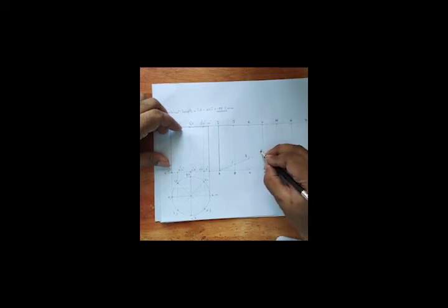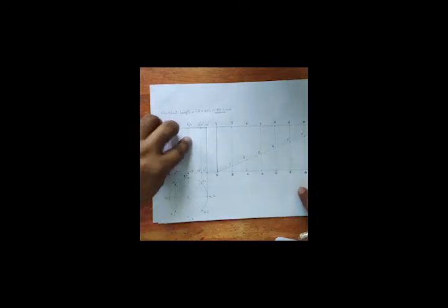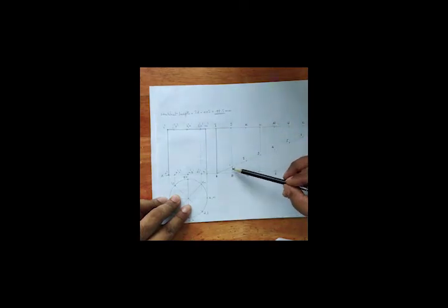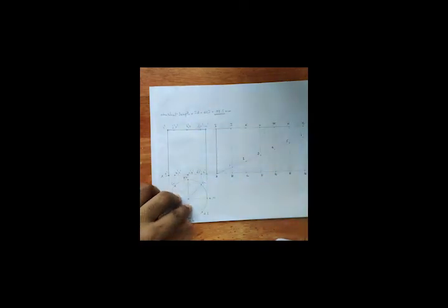This is point 3, this is point 4, 5, 6 and 7. We have 7 points. These are the points located in the development, and we have to mark the corresponding positions from point 1 to 7 in the elevation, so that will mark the position of the thread in the elevation.